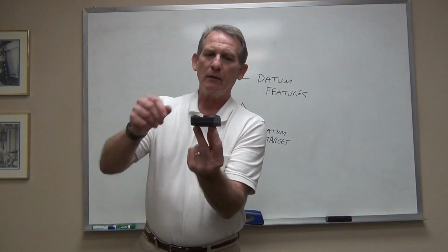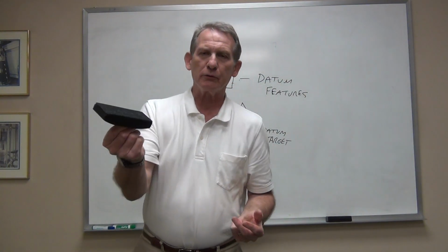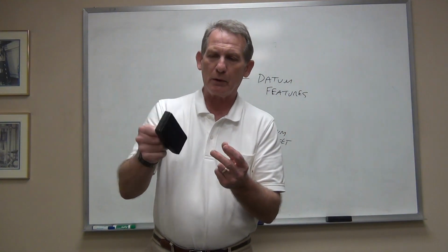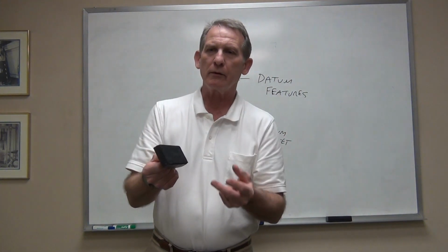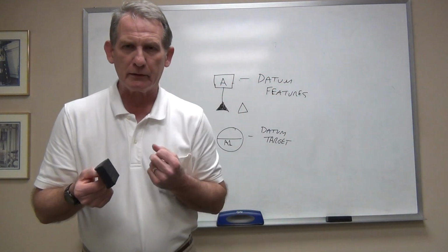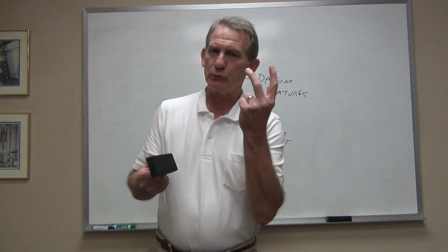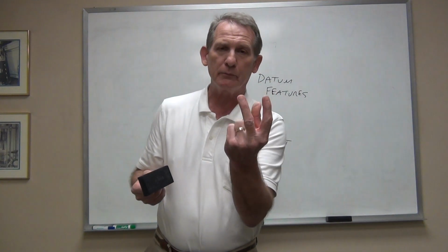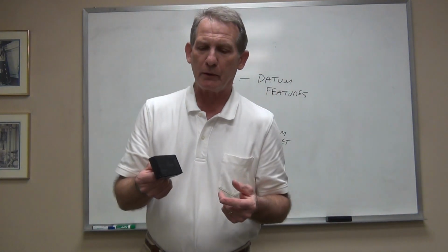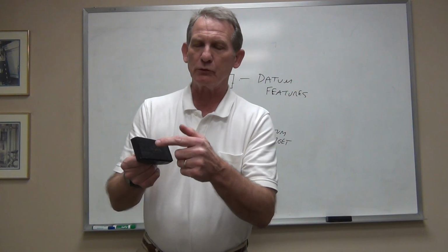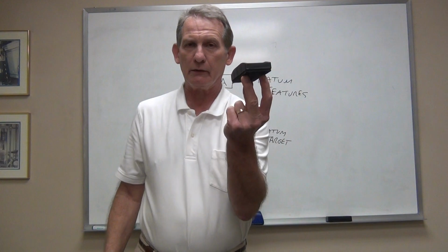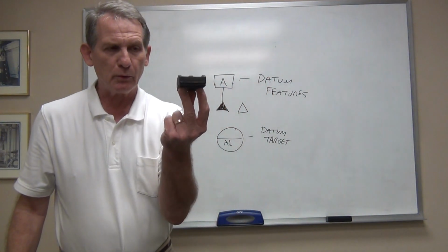When I pull the eraser off, there's no indication that I measured from or leveled the part on this surface or where. And that's the difference between a datum and a datum target, and that's why I need 3 datum target points here. So on a drawing I would show those datum targets, and I would provide measurements where those specific points are on the part, and we design a fixture to hold those parts.